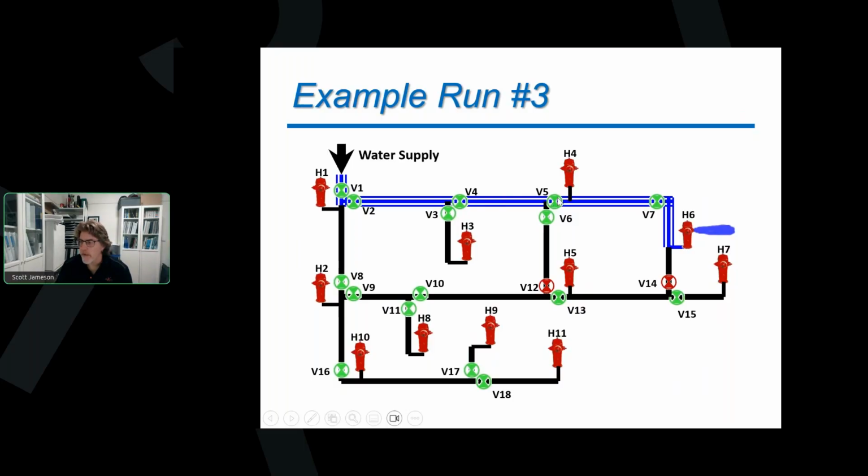And it might be quite dirty already by the time it's going past valve 5 and valve 6 in my system. Now, if there's anyone down here past valve 6 having a shower while I'm doing my flushing, I might be sucking some of that dirty water down that main, and they might get that surge of dirty water in their shower, their toilet, their bathtub, their sink, wherever they're using water.